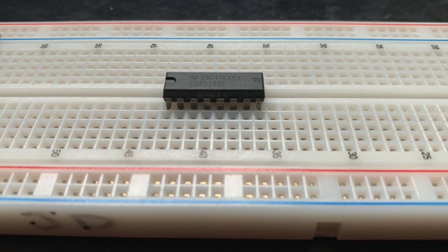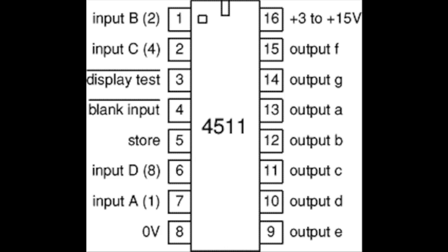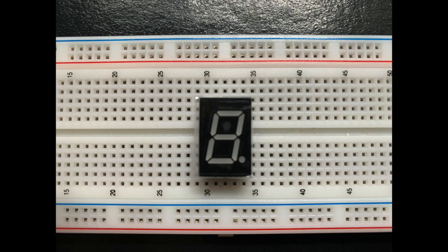The final circuit, part E, is the binary counting decimal decoder, where the final IC chip is introduced, being another specialized IC, the 4511 7-segment display driver IC. In this circuit, the common cathode 7-segment display is introduced, which will be displaying the values in a base 10 form.